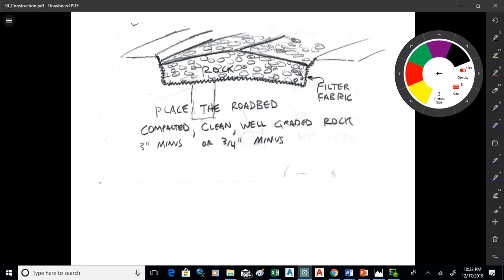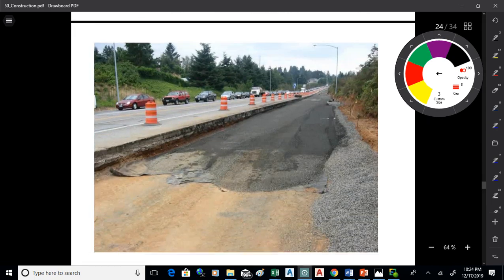Okay, I've worked in places where it gets quite cold, where they use a lot of fill on account of that. They'll start with 3-inch minus and work their way up to 3/4 inch minus. They might put 3 feet of fill below a road to get a good solid foundation there. Here in Western Oregon, we really don't have the temperature problems like they do in other places. So they'll use maybe, I don't know, for residential roads, maybe 9 or 12 inches of fill. So when they do that, they commonly just use all 3/4 inch minus for the whole 9 or 12 inches.